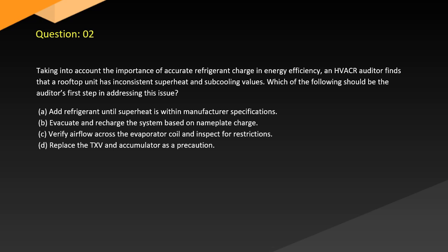A. Add refrigerant until superheat is within manufacturer specifications. B. Evacuate and recharge the system based on nameplate charge. C. Verify airflow across the evaporator coil and inspect for restrictions. D. Replace the TXV and accumulator as a precaution.